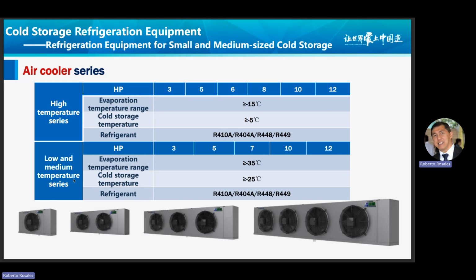For low and medium temperature series, it has a similar selection, which is from 3 to 12 horsepower, but the evaporation temperature is greater than minus 35 degrees C, and cold storage is greater than minus 25 degrees C. And a similar refrigerant of R410A, R404A, R448, and R449.